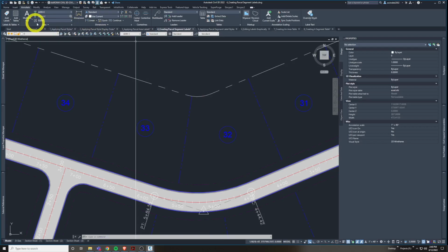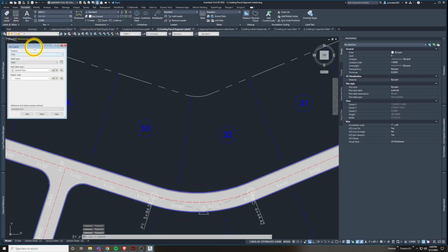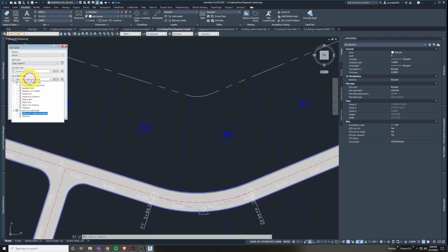And let's go back to our old friend on the Annotate tab and add labels this way. Let's keep this open, my favorite method. Go to Parcel, and Feature. Let's go to Add. Let's not change too many of these settings. Let's just accept the features parcel, leave most of the default settings in your line label styles and your curve label styles. Let's just start adding lines.